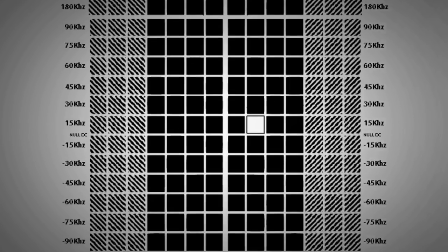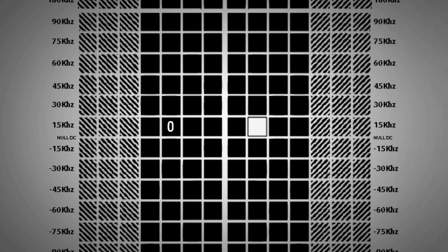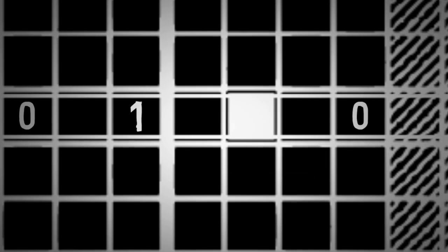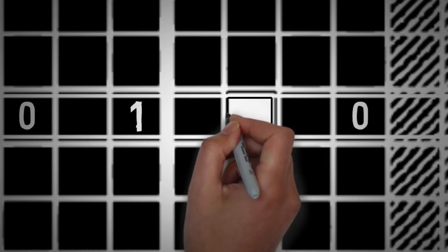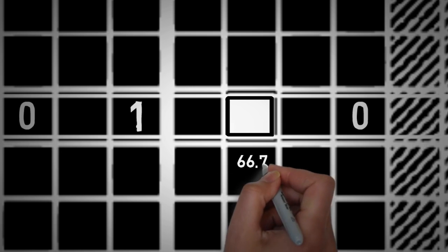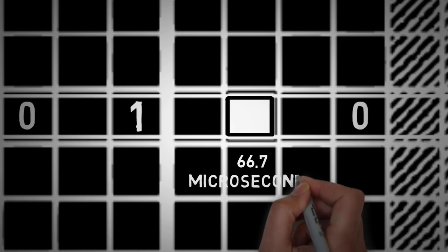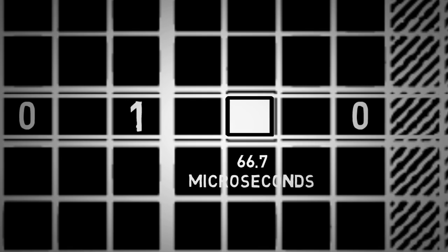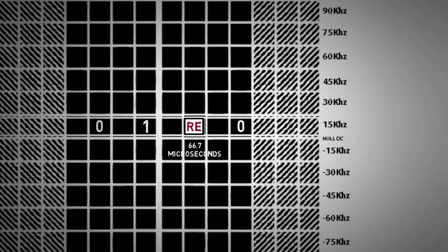Today we will discuss uplink and downlink data transmission in the network. As discussed earlier, data is transmitted in OFDMA over parallel subcarriers of 15 kHz. The subcarriers are further divided on the time axis as blocks of one symbol duration, or 66.7 microseconds. This basic unit is known as resource element. Each resource element carries one symbol.